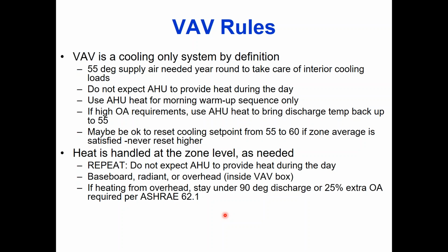I bring this up because many VAV selections we see from engineering firms will have coils already selected, and when we do the math, they end up being like 120, 130-degree discharge air temperatures, which is never going to work. So we need to back those down and put in either smaller heaters or more airflow, depending on what's needed.